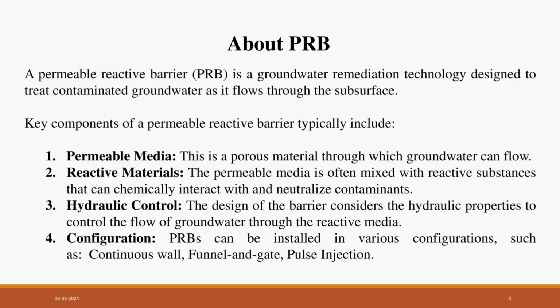The permeable media is often mixed with reactive substances that can chemically interact with and neutralize contaminants. Then hydraulic control. The design of the barrier considers the hydraulic properties to control the flow of groundwater through the reactive media. And the fourth one is configuration. PRBs can be installed in various configurations like continuous wall, funnel and gate, pulse injection, etc.